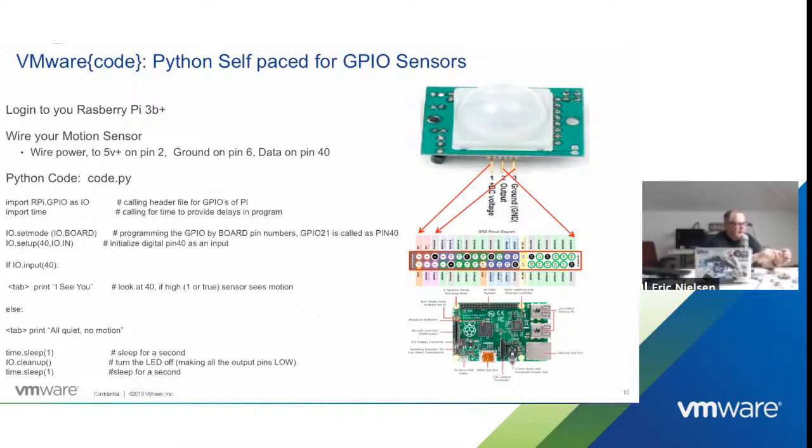Notice this sensor has 2 variable little dials on it. You can't probably see those, but they're orange and they have screwdriver slots. One is for the sensitivity because it is measuring movement in the room. And the second one is how far out do you want it to look, because light is time. It matters if you're measuring a 1-inch space versus a 15-foot room. This will do a 15-foot room. It'll actually do a 20-foot room, so it'll go out 10 feet in any direction. So these are a nice thing, but you do have to set the sensitivity and the distance with those 2 little settings.